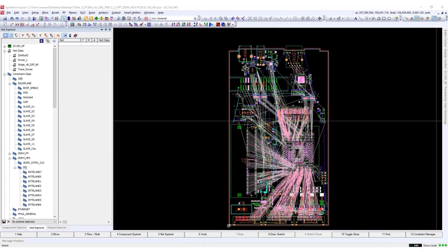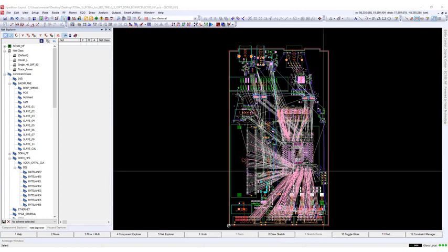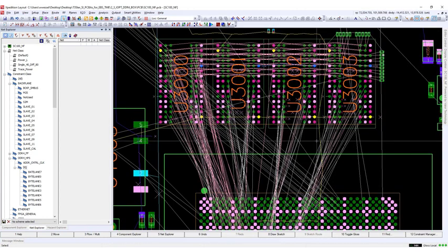Based on the component placement, I want to pre-optimize the FPGA pin assignment to reduce the breakout and fan-out effort. These steps help us to identify channels much easier and allow us to make good design decisions about routing layers and sorting of signals. Netline filtering helps me to define a strategy up front, and I can set the focus